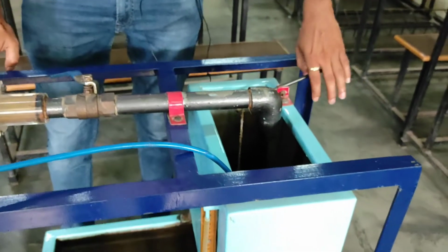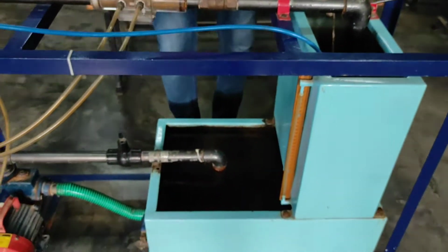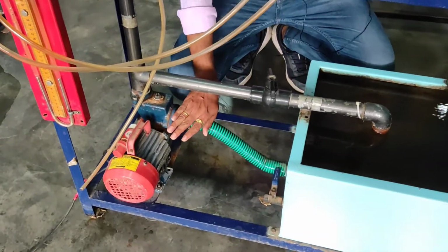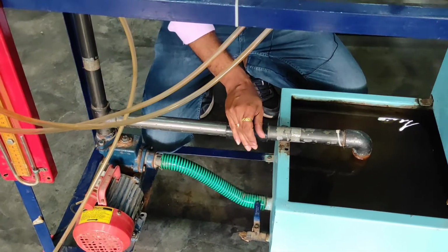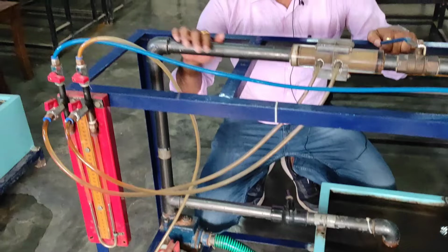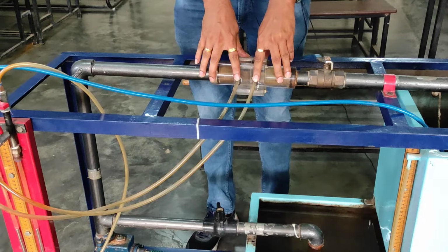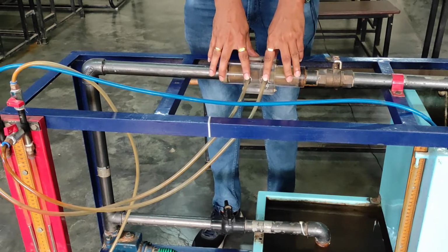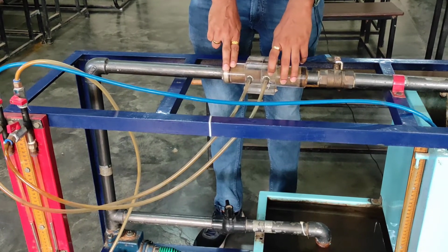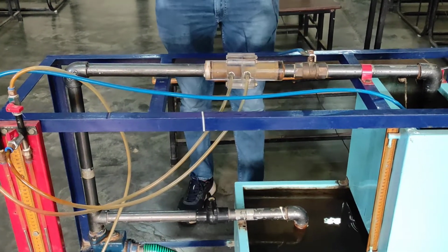This is the discharge tank. We have a lever operated valve over here. Then we have a reservoir tank over here. From the reservoir the water will be fetched with this green pipe through this motor, right? This is the bypass valve. You can control the flow of the water to the suction pipe through this bypass valve. Then again suction pipe is there, and one more thing, two pipes are attached over here to the U-tube manometer filled with mercury. One is attached to the main pipe cross section and the other is attached to the vena contracta after the orifice section. So these all are the components of our setup.